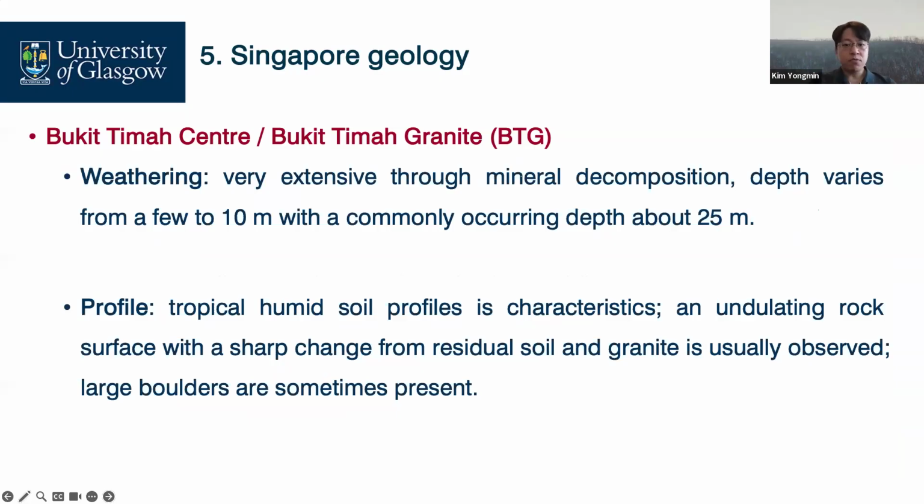That's why the Bukit Timah Granite underwent a severe weathering process, mechanical and chemical weathering. It may cause high variations of depths and soil characteristics from residual soil to granite. That's why the main characteristic of Singapore soils is residual soils.